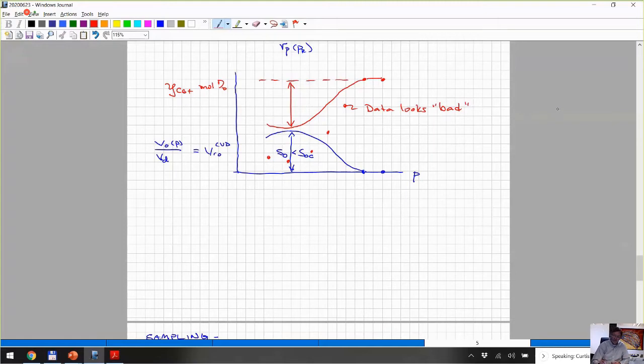So if that data looks bad and you only have one sample, then you're obliged to fit this. It's difficult to know; that's the problem. But we had one customer with literally over 100 samples and none of the removed gas compositions were reliable. So we had to use the liquid dropout curve for every one of them in developing the equation of state.